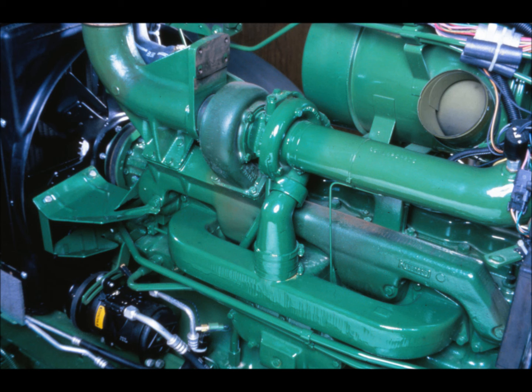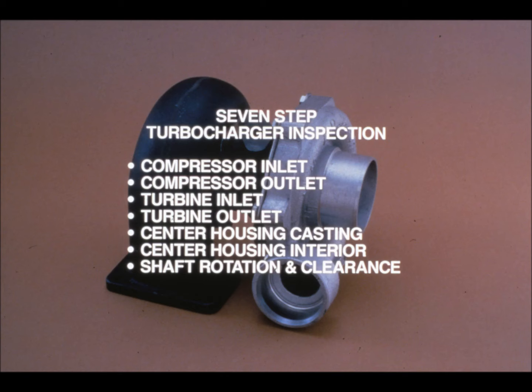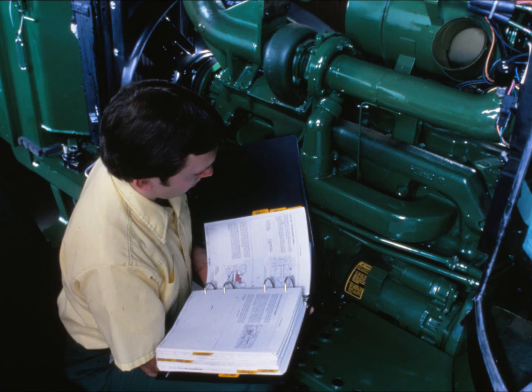That completes our review of turbocharger design, operation, and failure modes analysis. Before you replace a turbocharger, complete the full 7-step diagnostic procedure. Trace the source of the problem, the underlying cause of a turbocharger failure, and be sure to correct the underlying problem before replacing the turbocharger. Provide your customer the best service and operation possible. With an adequate supply of filtered air and filtered lubrication, a turbocharger will provide that customer with excellent performance for a long time.